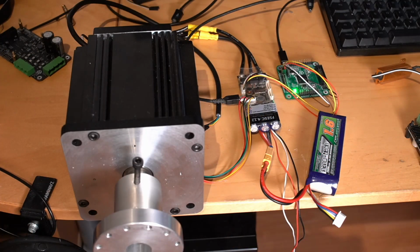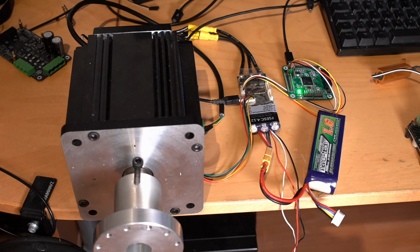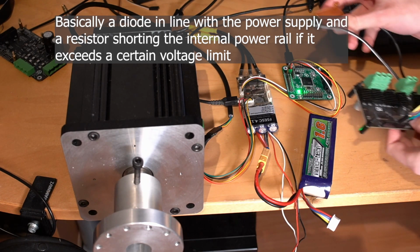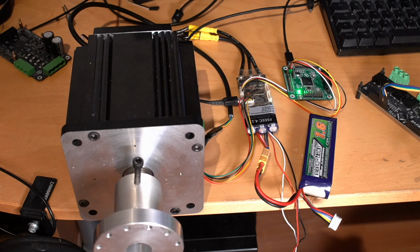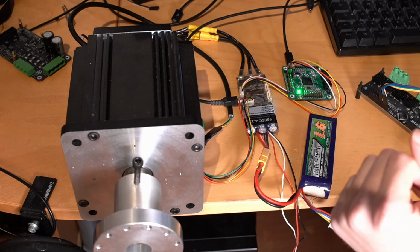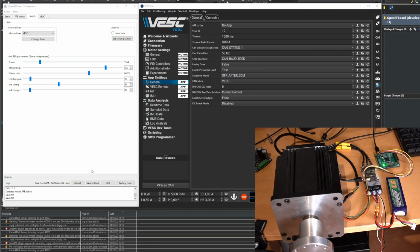I have now connected a VESC to a battery and our FFBoard with the CAN bus connection. The encoder is also connected to the VESC. And you have to take care to use a battery or a brake resistor circuit, which you have to design yourself, because unlike the ODrive and also the TMC, the VESC is made to be powered by a battery and doesn't have a braking resistor and protection diode for the power supply. If you were to connect a power supply to the VESC and turn the motor, then this would feed back power into the power supply and very likely trip the overvoltage protection of the power supply or even damage it.